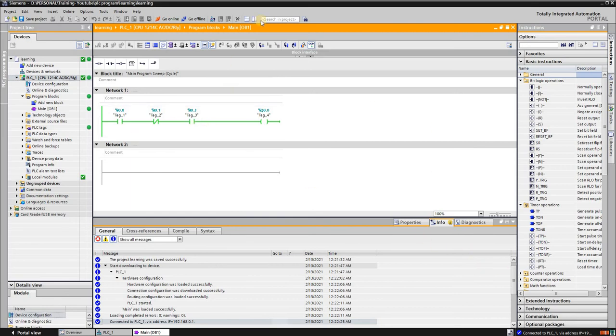So how you gonna do it is this again. Here we have timer operations. If you want to run the timer at least for 10 seconds, in that case we have to use an off delay timer. So what that means is, how the off delay timer works is, when you have the signal, when the input of the off delay is enabled, and then the input is gone, it's still active for 10 seconds or a predefined time, whatsoever it is.